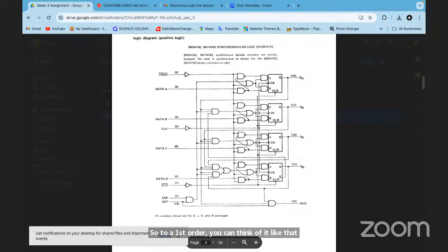If I draw more current, then the voltage has to drop, because V into I is the power and multiplied by time is the energy. So if the current that the ADALM is driving increases, then the voltage will drop. That's why that counter was not working when driven by ADALM directly.